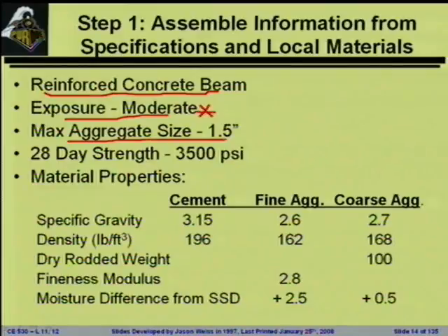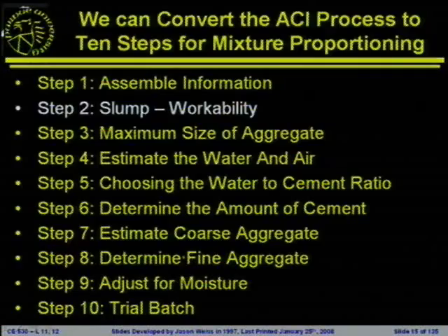Maximum aggregate size that we'll use is 1.5 inches. We'll shoot for a 28-day strength of 3,500 psi, and then I've listed all of the different material properties that we'll be using down here. So we've got the specific gravities of the materials, the densities of the materials, the dry rodded weight, fineness modulus, and the difference from a saturated surface dry condition.